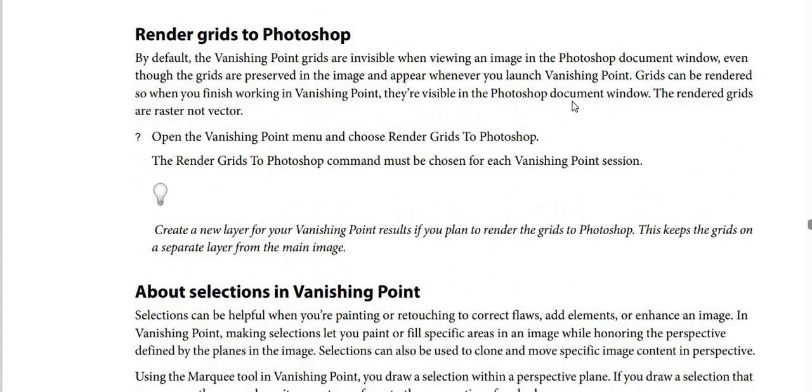How to render grids to Photoshop. By default, the Vanishing Point grids are invisible when viewing an image in the Photoshop document window. Even so, the grids are preserved in the image and appear whenever you launch Vanishing Point, and the grids can be rendered.